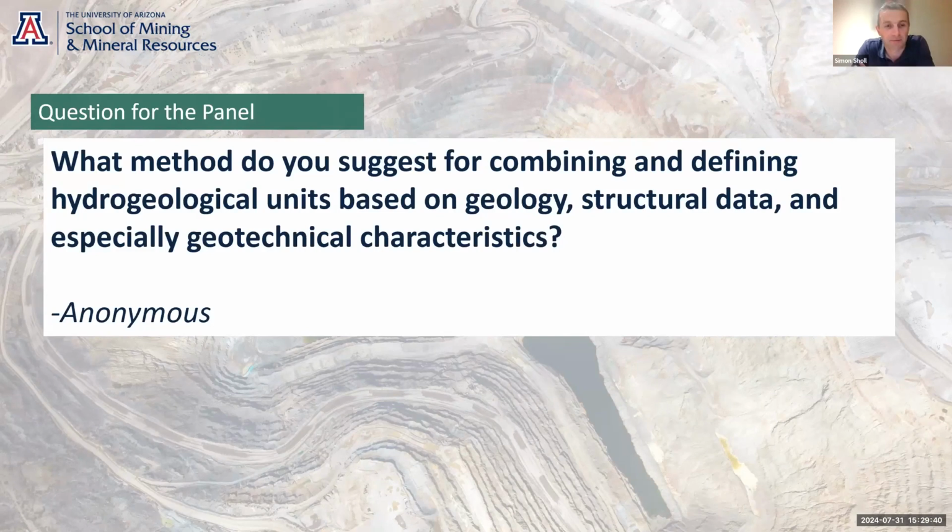Just going to add, absolutely agree with everything that's been said so far, but I'm also a big fan of trying to keep it simple where you can. So think about what the conceptual model is being used for, and make sure that you apply the level of detail that's required for whatever question is being asked of it. For example, if it's going into a regional 3D numerical groundwater model, what do you believe that the smallest cell size might be?